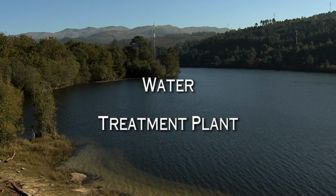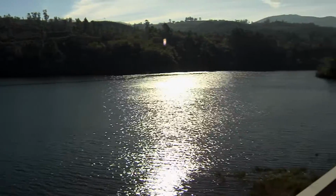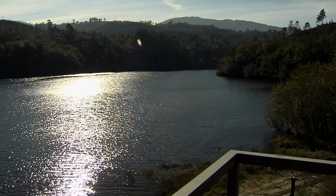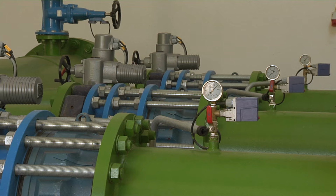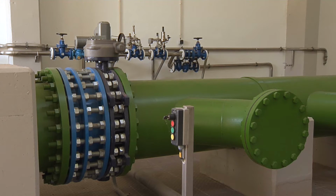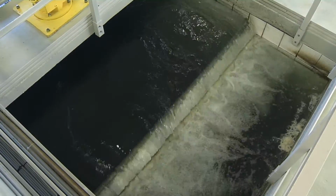Water treatment plant. This water treatment plant is sized to power about 260,000 inhabitants, which corresponds to a maximum flow of 2,700 cubic meters per hour. Water is collected in the dam at a depth of 10 meters and raised for water treatment through a 700 millimeter diameter conduit. Pumping groups consist of 3 submersible electro-pumps of 630 kilowatts each and unit capacity of 960 cubic meters per hour.